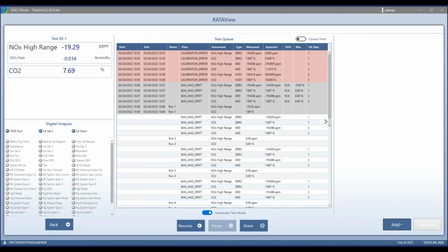What were the other questions? Are you planning to incorporate the new data fields required by the electronic reporting rule that will be required starting in the first quarter of 2023? I assume that's referring to the new JSON format instead of XML. Yes, we will be doing that. That's all done inside of the spreadsheet. There's a tab in there that will generate the emissions or the RATA XML file. Yes, we'll be updating that to report as a JSON format.